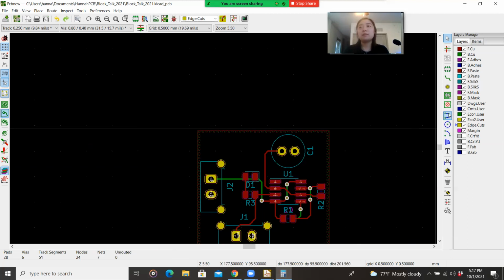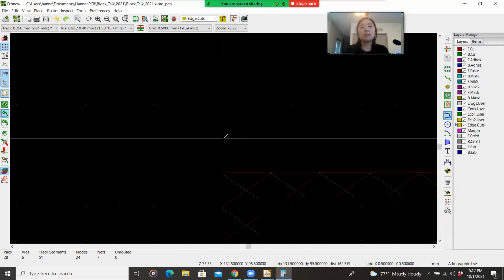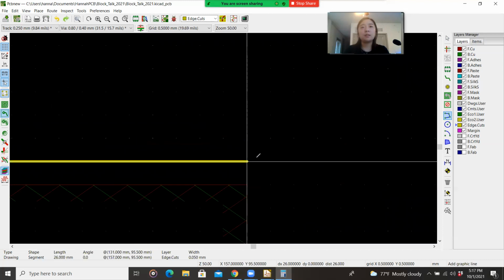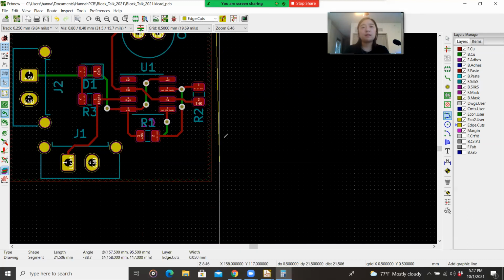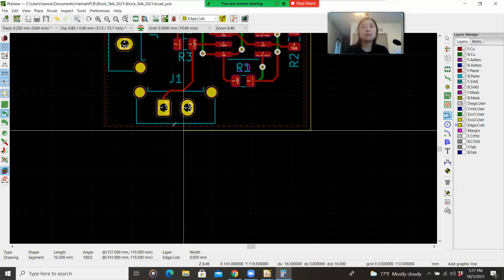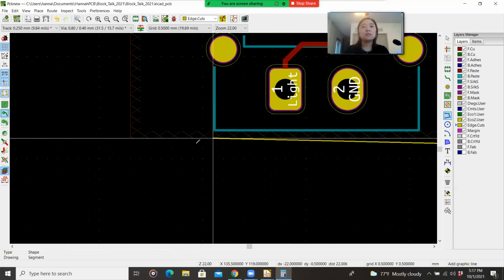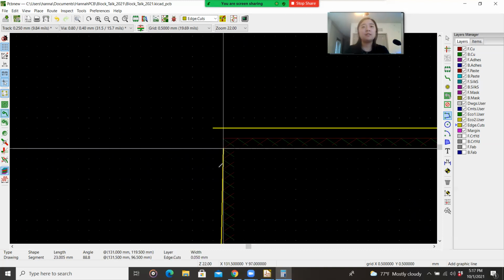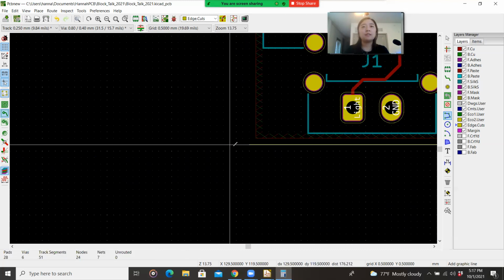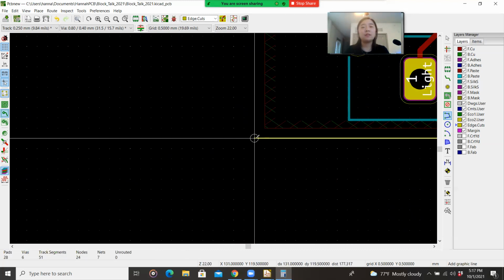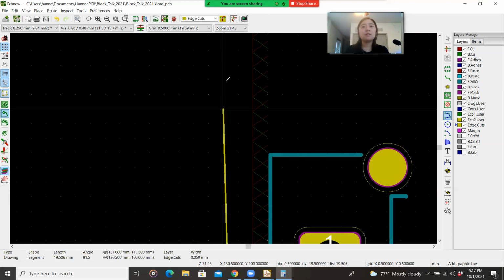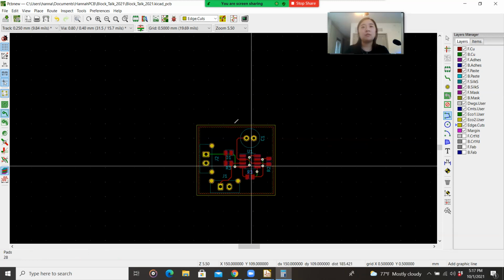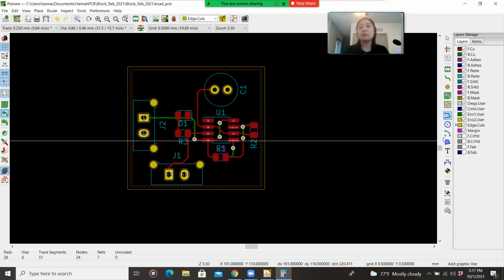copper plane. So sometimes it's a little annoying because you want to access the edge cuts, but it doesn't allow you to. So let's make it just slightly bigger so that we can touch it. And so we'll just repeat what we just did here. You always want to make sure that these are straight, because you don't want a rounded edge board. That would not be good. Or a crooked edge or anything. You want to make sure they're straight.